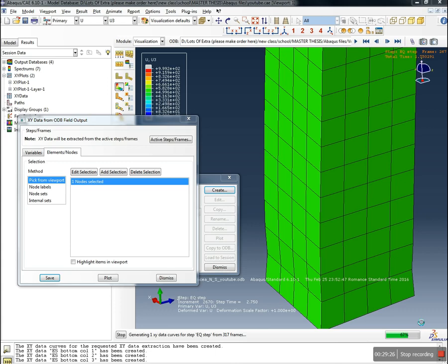Also to avoid the shear failure. Obviously in our model we don't have any stirrups, but you can do it. You can just try to do the same model, put in stirrups, and compare the response of the structure with stirrups and without stirrups. What you're supposed to see is that the strains are much lower when you use stirrups. But obviously you have to use stirrups everywhere because that's how reinforced concrete frames work.